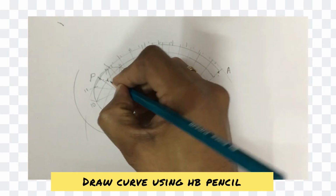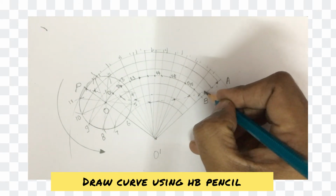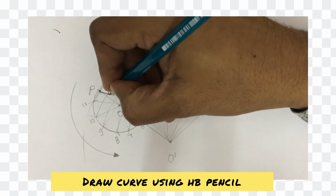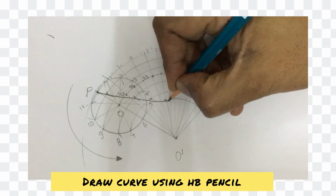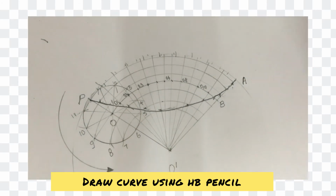This is P1, and just join all these points using dots, and then join this. Then join all these points, sharpening your HB pencil so that you are going to get a very neat curve, and that curve is said to be a hypocycloid.